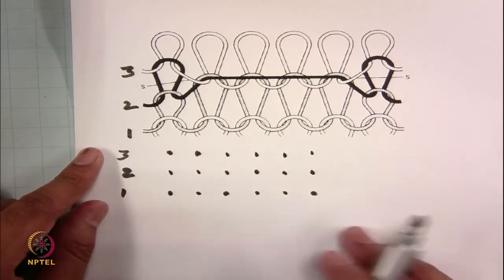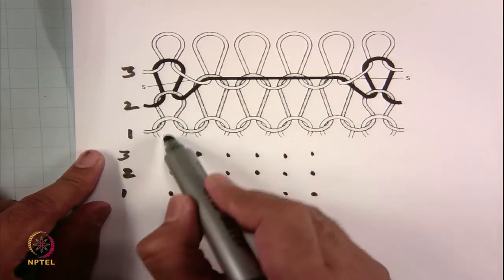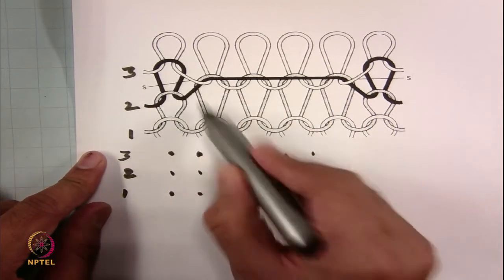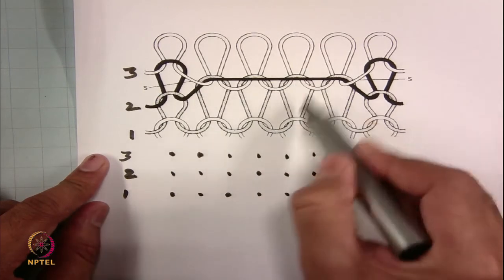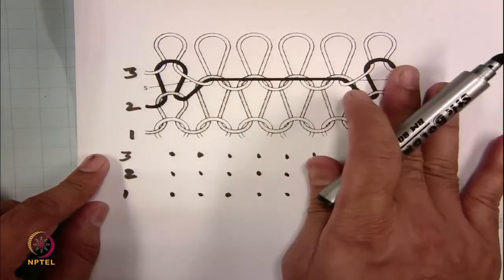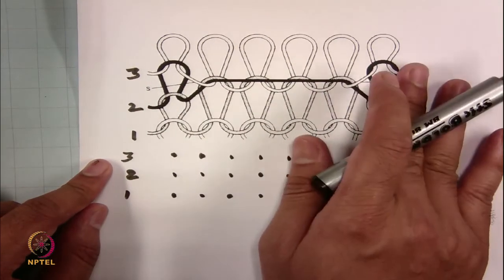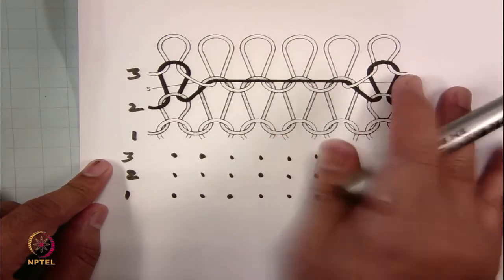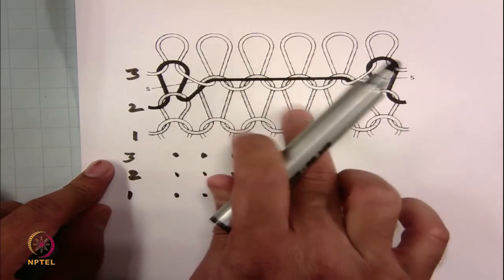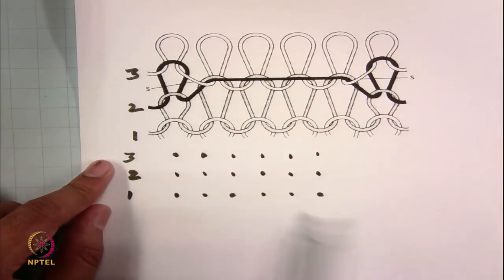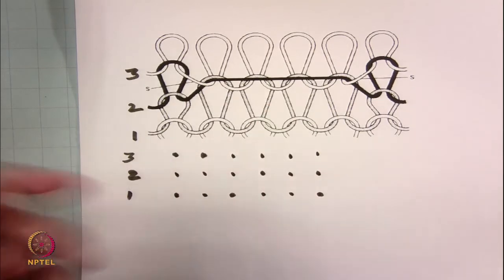Third course. Why are we using one set of needles? If you carefully see all the loops, this is also technical backside, the second needle is also making technical backside, the third needle is also making technical backside. So, all loops, all needles in this particular fabric are towards the backside. That is why it is made by a single bed machine. So, this is also a single jersey fabric, and you have 3 courses which is visible here, and it is made by 6 needles.